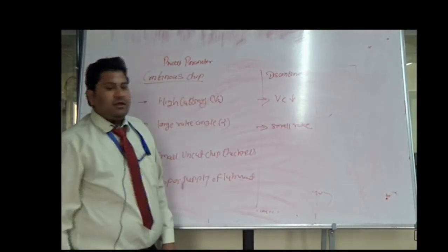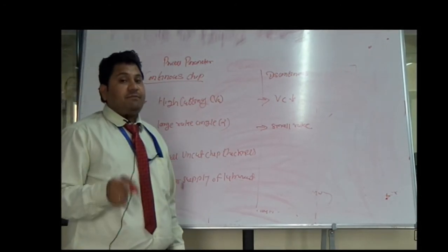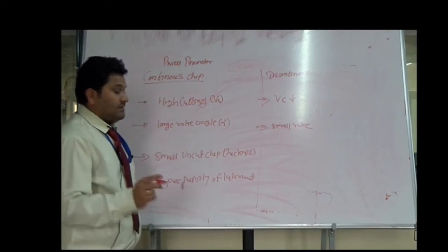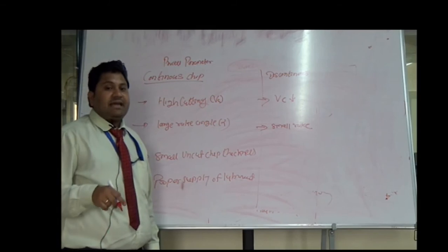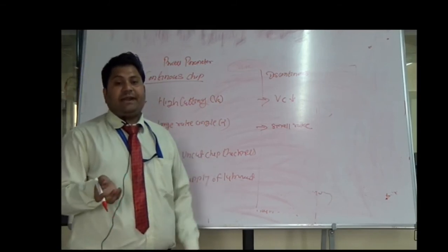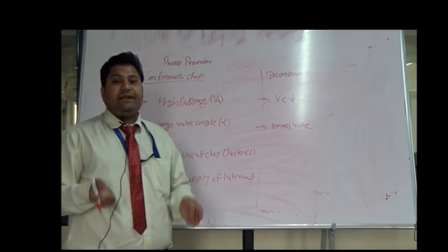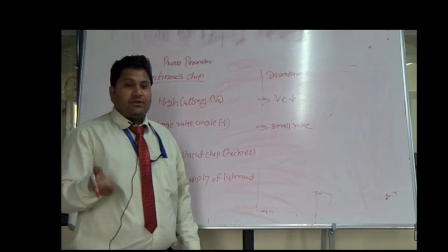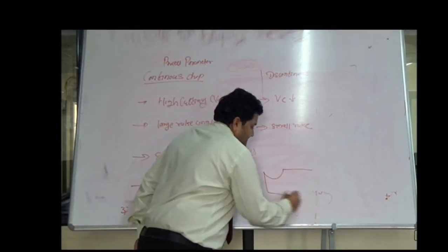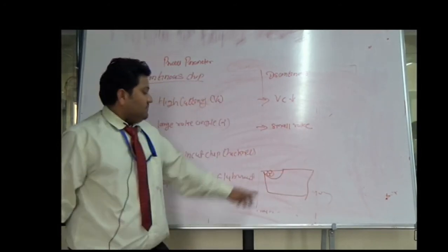The rake angle is very important. What are the effects of these angles during machining? As we saw in the previous section on the mechanism of chip formation, the chip flows plastically in front of the rake face of the tool. So the rake angle, denoted by alpha, is very important in machining action.